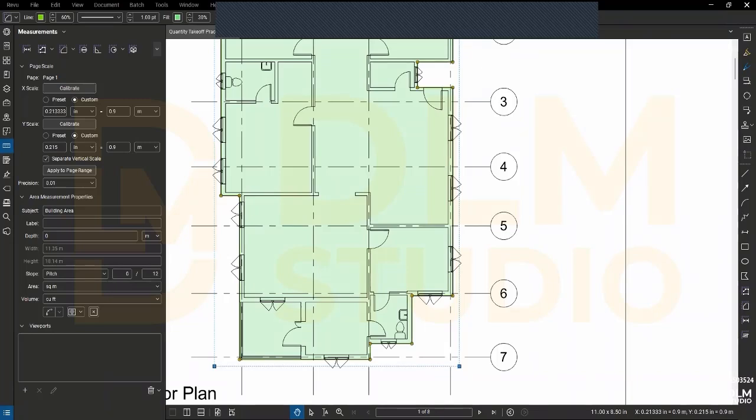So when we scale it, we can convert it to the scale that is accurate with the drawing. Once you scale, I will explain how to calibrate now. Once you calibrate your PDF, do your measurement, it's accurate. If you calibrate the right way, you get the right measurement. If you calibrate the wrong way, you get wrong measurements. So basically, it's what you calibrate that you get.